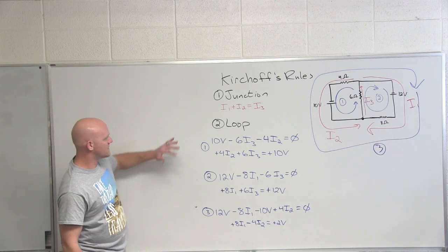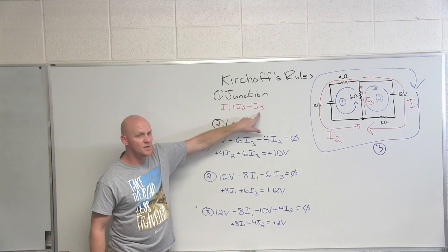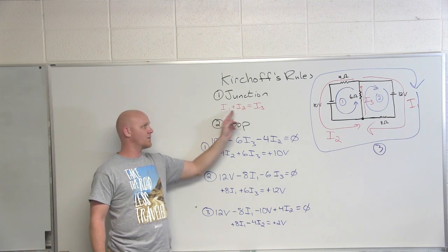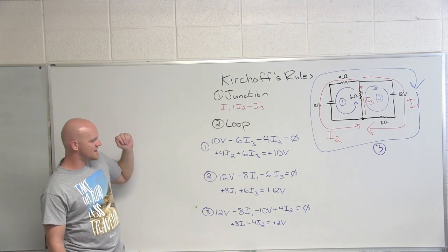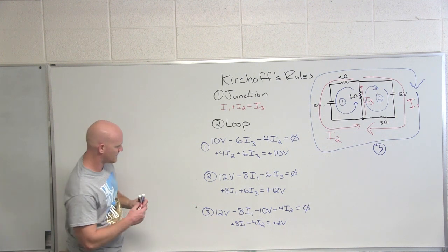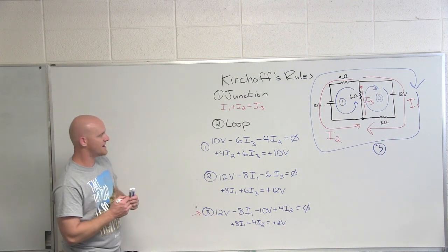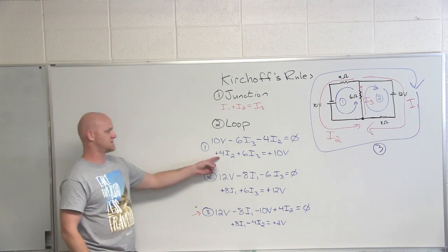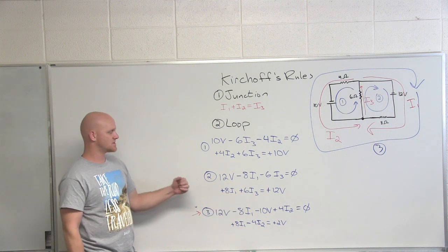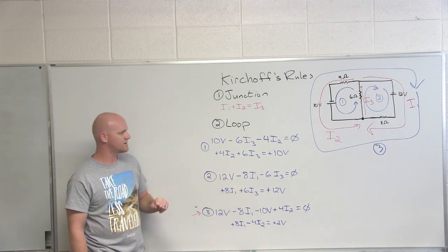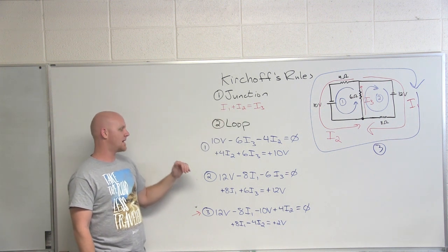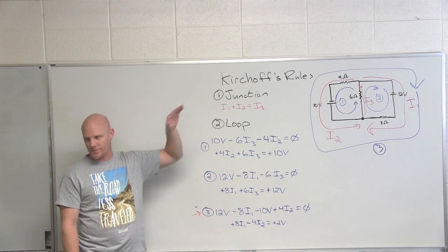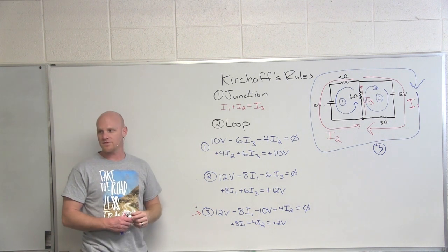All right. So a couple things we can do. I know I1 plus I2 equals I3, which would make it really easy to substitute into an equation that has I3, and substitute I1 and I2 into it. So in this case, which equation has I1 and I2 in it? Good. Is there an equation that has either just I1 and I3 or just I2 and I3? 2 and 3, or here 1 and 3. Because if I substitute either here or here for I3 as I1 plus I2, then I would have an additional equation that only has I1 and I2 in it, just like our third loop rule, and I'll be able to combine those in one way, shape, or form to solve for those 2 variables.